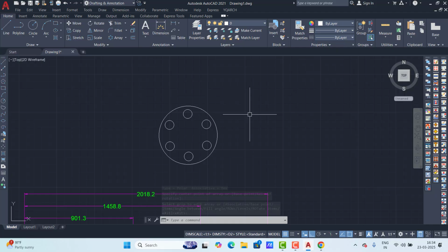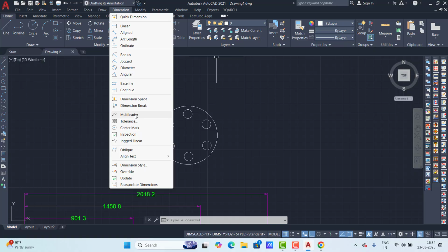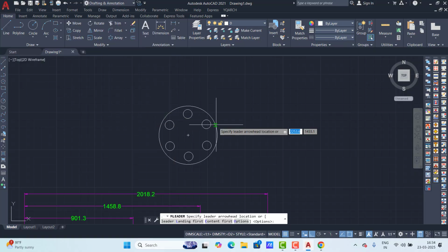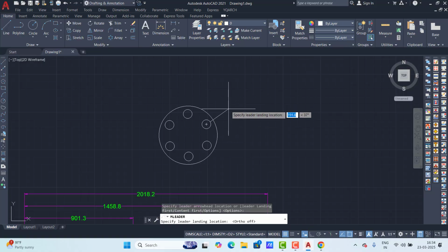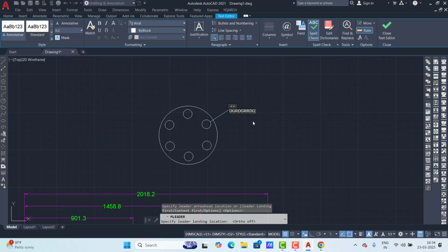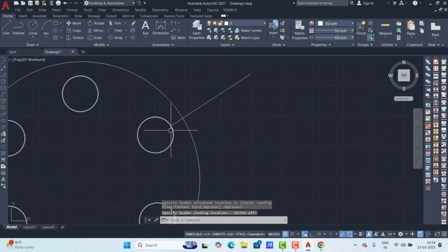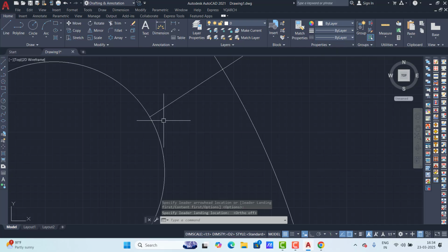Now just finish the setting. So this is the Leader 1 style. Suppose next I want Leader 2. Here only we complete the leader structure. Suppose I want to complete in 2 steps, so we put 2 steps here. Otherwise if you want 4, then 4. Leader content height: suppose here 60. Otherwise you type 100, so you put 100. For leader format, you put leader structure 25 and click OK.